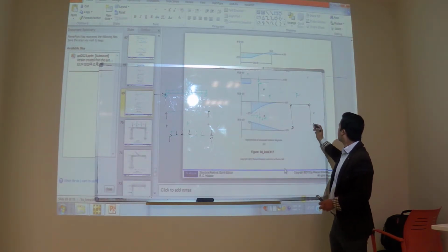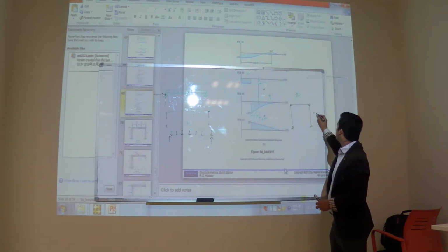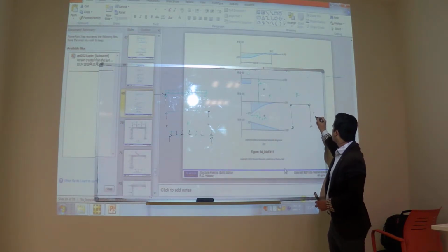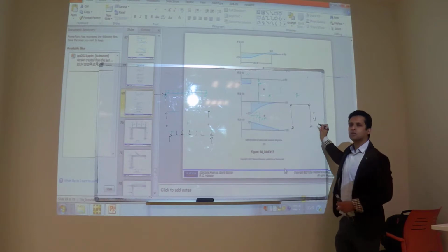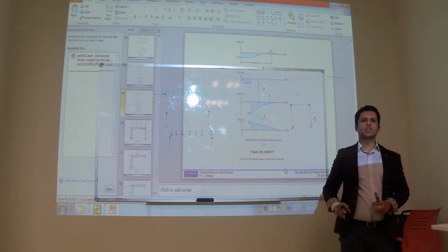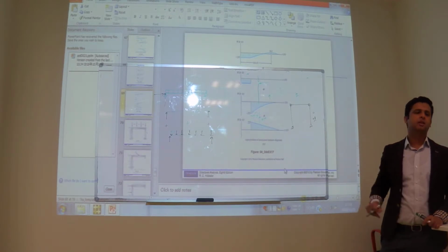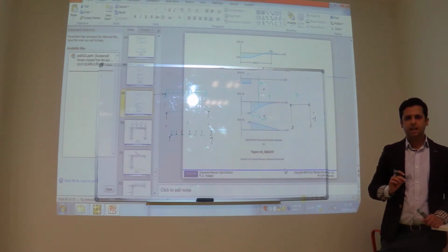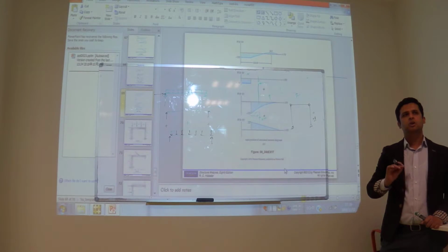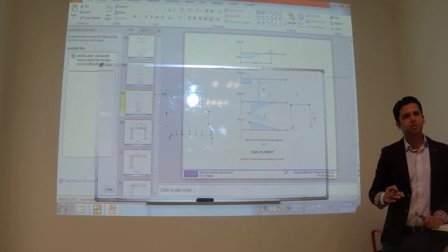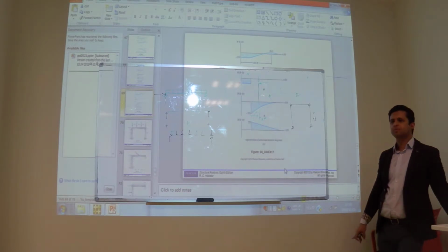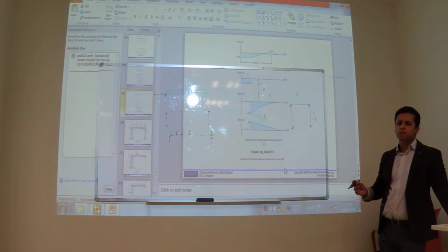But if you make even 2 hinges, now the degree of indeterminacy will become +1, and you cannot solve this frame by these methods. In that case, you have to use a special method, the finite element method. Or there are some other methods for indeterminate structures.